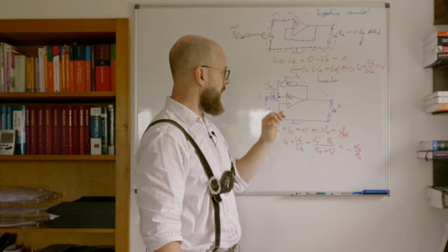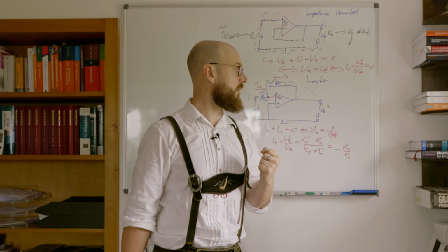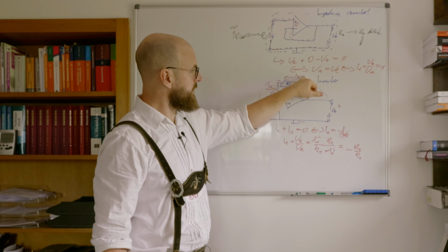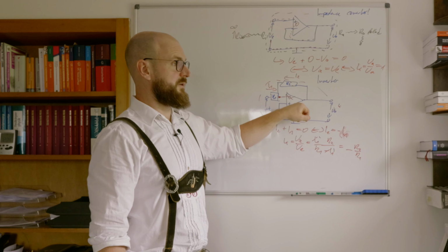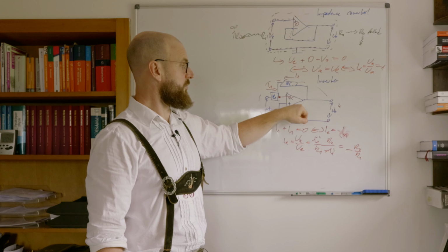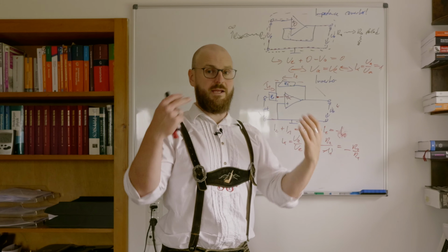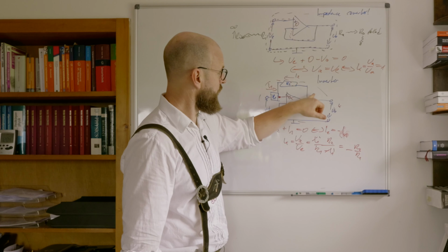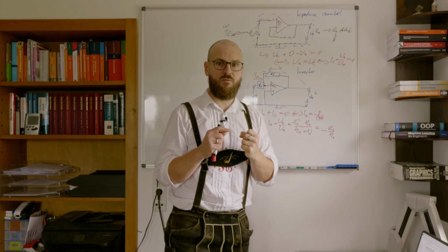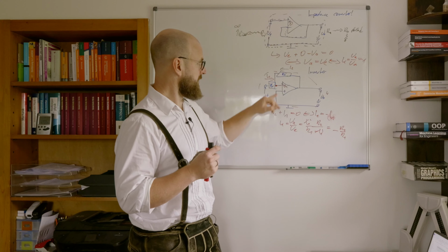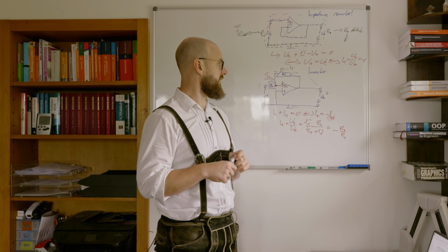Having said so, normally you would not use that electrical circuit for amplification because the whole current I2 has to come from your operational amplifier, from your external voltage source. And normally those operational amplifiers aren't able to generate high currents. So, doing so, we are somewhat restricted with the amplification factor by the current which we have to deliver at the output of our operational amplifier.